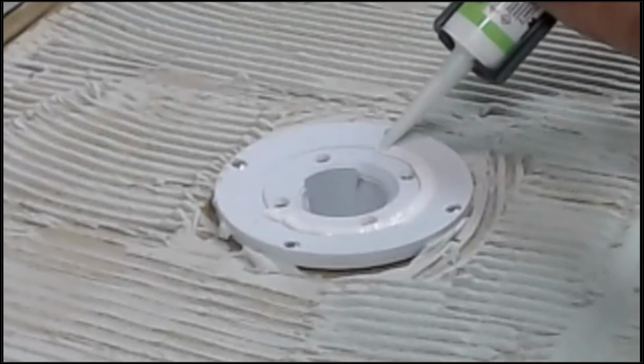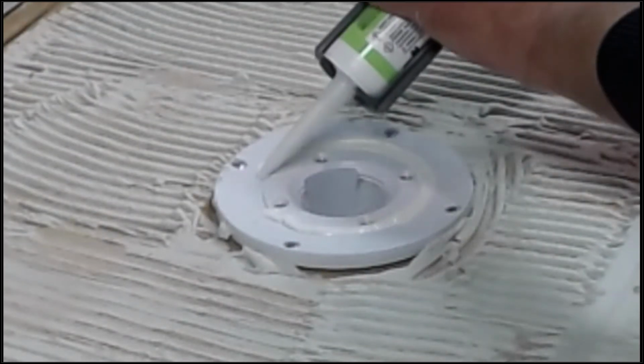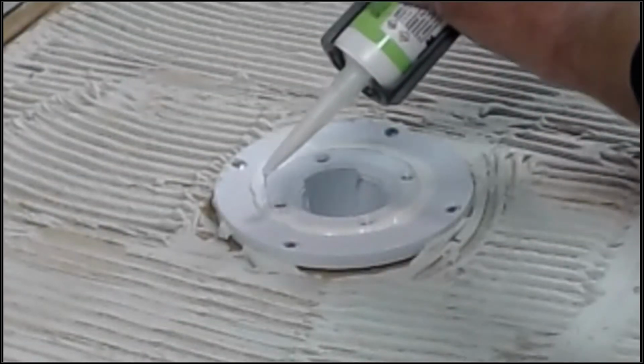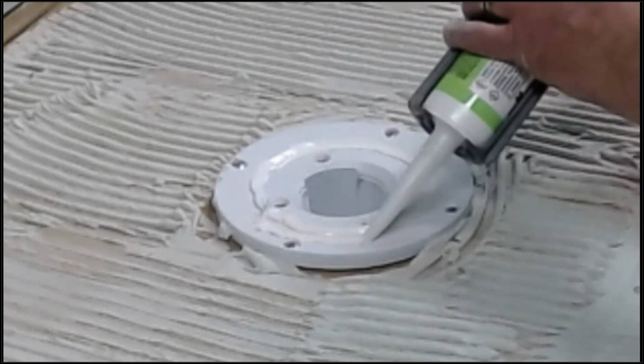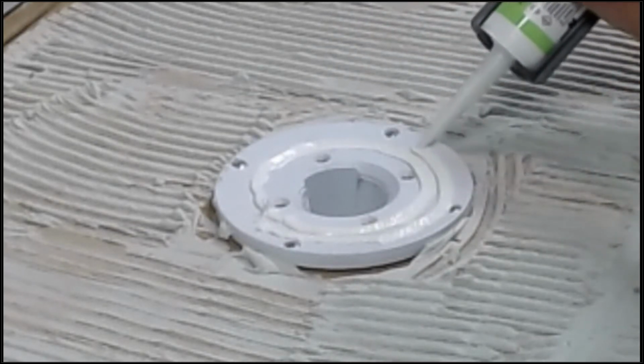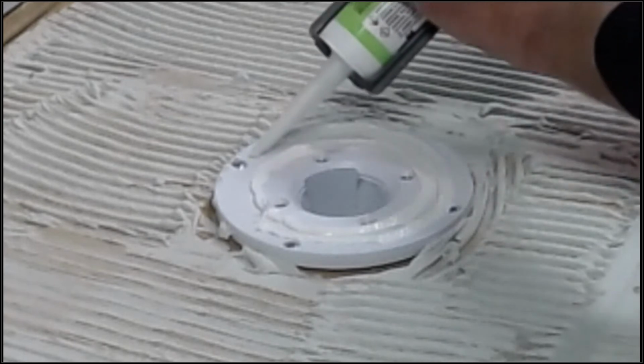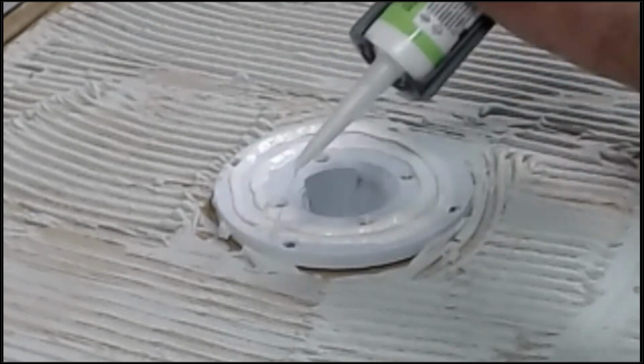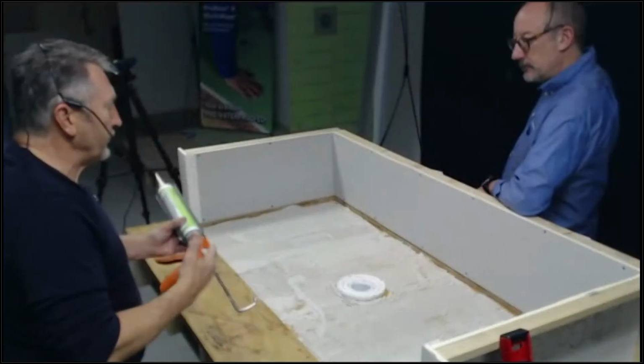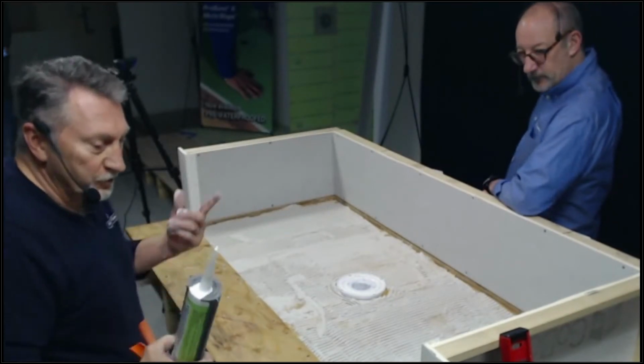If you choose to use the sealant as your seam sealer and install your corners, you can immediately flood test with this. That's an option for you if you want to flood test that same day, instead of using modified thin set to do all your seam sealing. You can still bond your membrane down with a modified thin set, but then just do your seam sealing with 250 sealant.